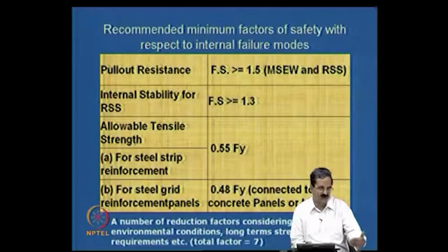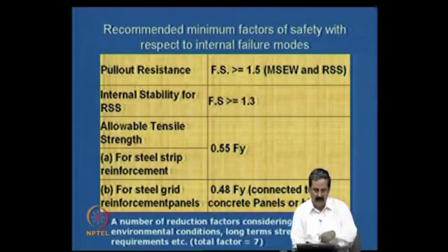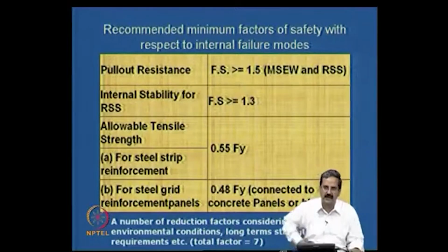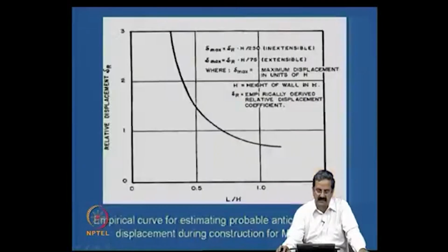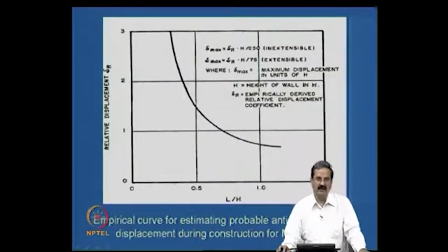Now if it has been done, you take the sample and test it, and if it shows 140 kilonewton per meter, then it's fine. Then you also have information about all these reduction factors, and you use those reduction factors correctly, and then you will get the correct long term strength, and you can say that yes, the design is satisfactory.